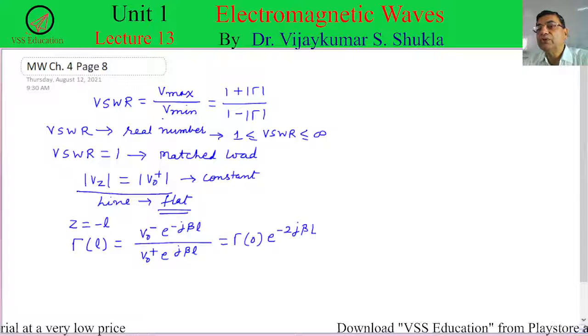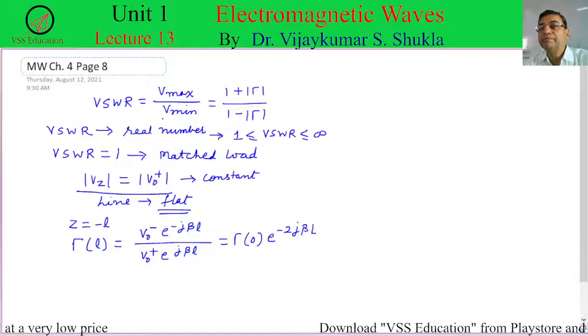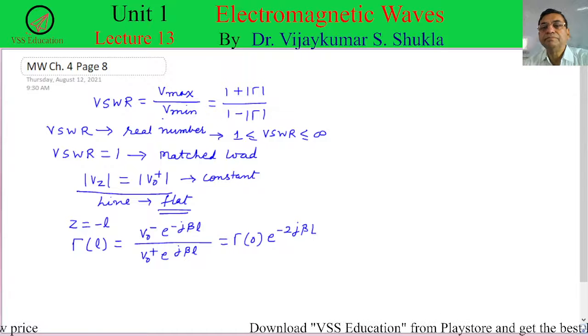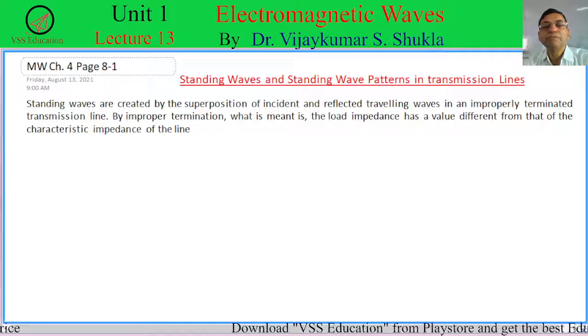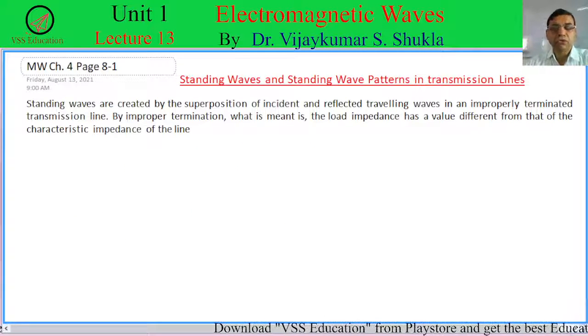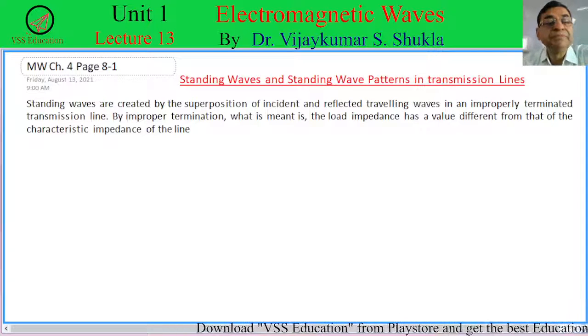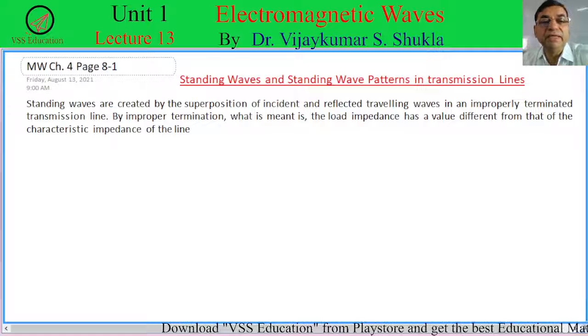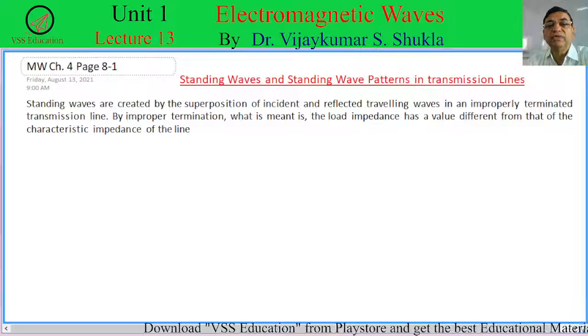Now today we'll see about these standing waves and standing wave patterns on transmission lines. Okay, so today we'll see this. Now what are standing waves? Standing waves are created by the superposition of incident and reflected traveling waves.